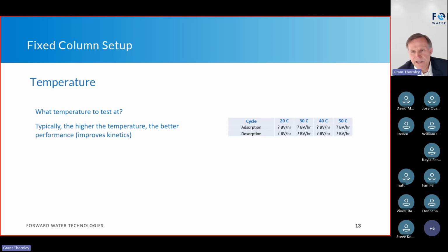The other aspect, a side note on absorption and desorption, is that sometimes people ask, okay, for desorption I'll heat it up, and for absorption I won't. Just so you know, this is a solid media or material, and if I have a very large temperature gradient between my absorption and desorption, I can thermally shock the media and cause it to fracture.